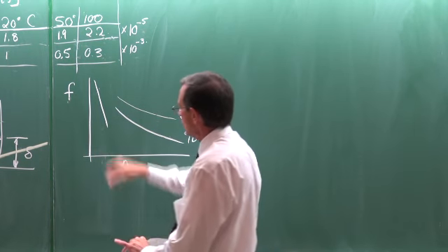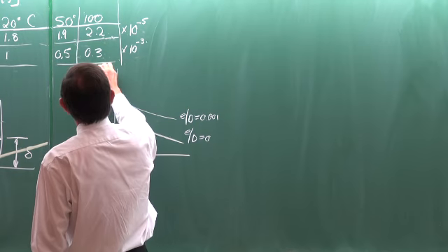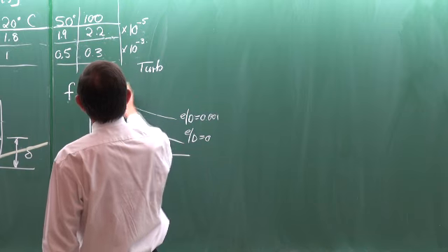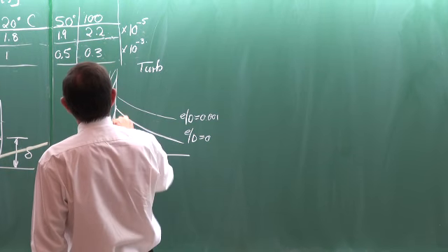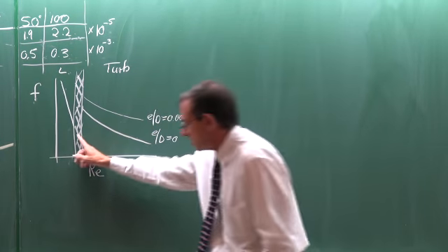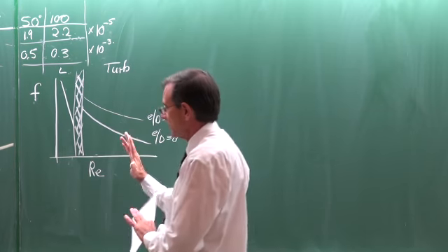So this is in the laminar flow regime. Remember, that is laminar and that is turbulent. And this is transition. So if you look in your Moody chart at the end of your textbook, you will see a gray area like that. Why? Because they say, well, stay out of it.